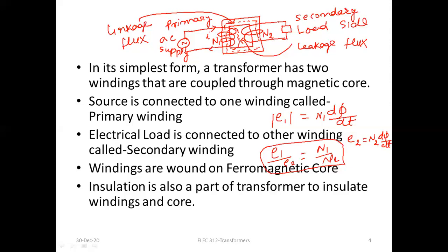If you do not give insulation, they will be mechanically and also electrically in contact, a short circuit will take place and the winding may burn. To avoid this burning, we isolate the windings from each other by means of insulator. The same thing we are also providing here.